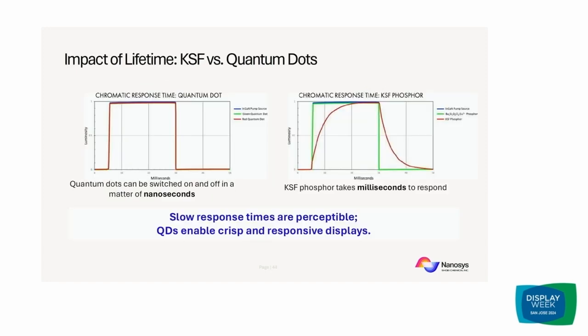So the third aspect here is an advantage of quantum dots for displays, and again, that's their exceptionally fast radiative rates. So it's possible for quantum dots to respond in nanoseconds, which is essentially instantaneously to the human eye, to changing excitation light, so to exciting the system with a higher energy excitation wavelength.